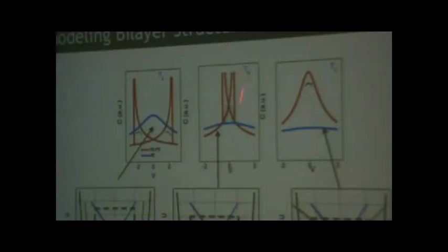But as I increase temperature, at some point I go into a situation where my red curve is above the blue curve, which means the heterostructure is giving me larger capacitance. This is the negative capacitance region. But I still see some hysteresis. I keep increasing temperature, the hysteresis will go away, and I will start seeing very large non-hysteretic negative capacitance.